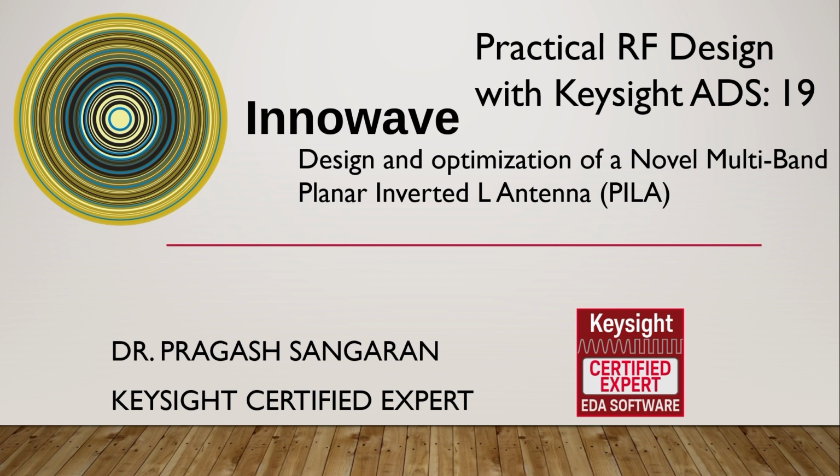In this tutorial, we will learn the complete design and optimization guide for a novel multiband planar inverted L antenna. This antenna is implemented on a rigid printed circuit board. This antenna covers 617 MHz to 960 MHz, 1.71 GHz to 2.2 GHz, and 2.3 GHz to 2.69 GHz.